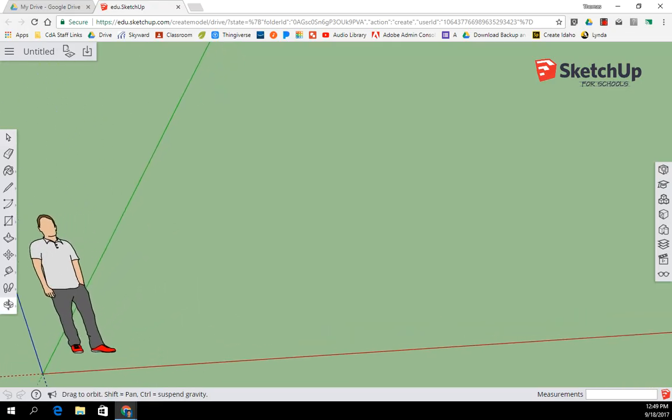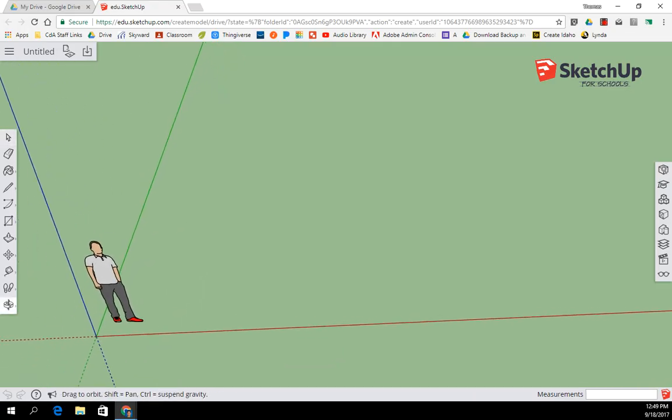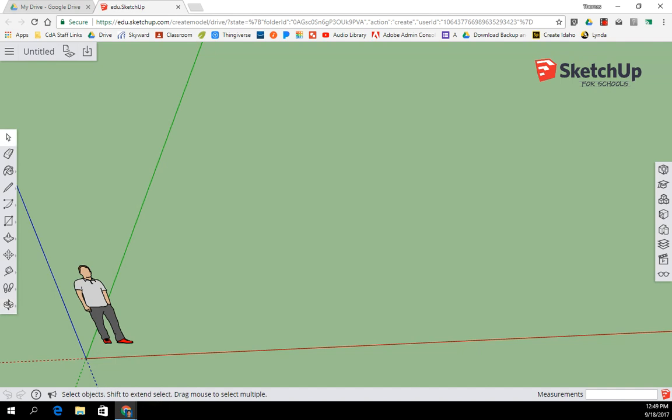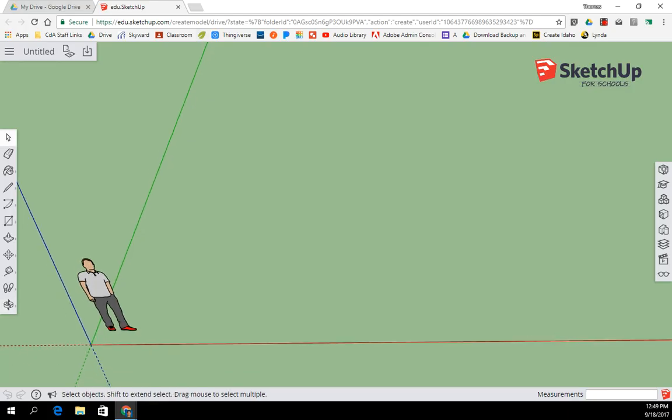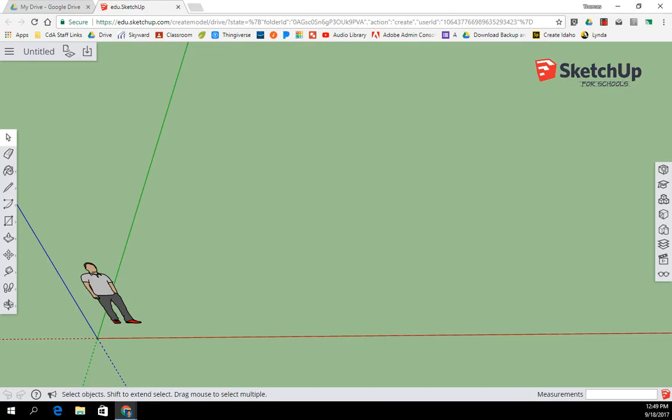Now we're going to move the camera. So our reference material is in the bottom left-hand corner. Here's the origin. Your blue line comes up here. Your green line goes up through the top. And then your red line kind of goes right along the bottom there. And you kind of want to be looking downwards. Now we're going to start by drawing the 6 foot by 6 foot square. The symbol for foot is apostrophe, which is right by the Enter key on the keyboard.